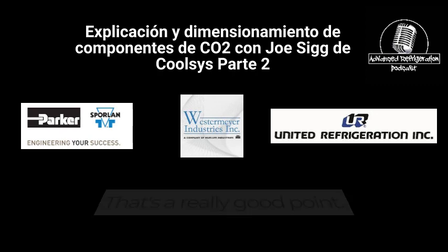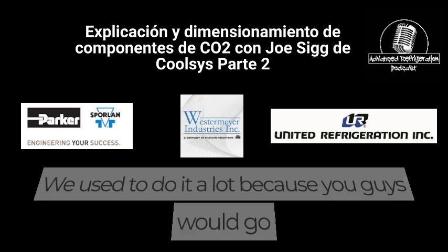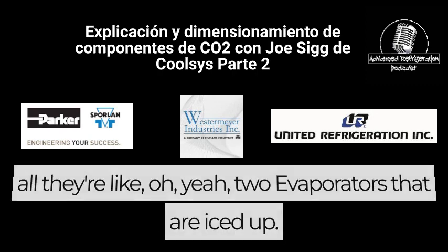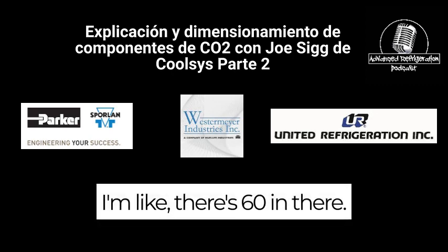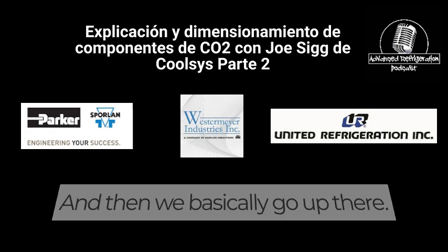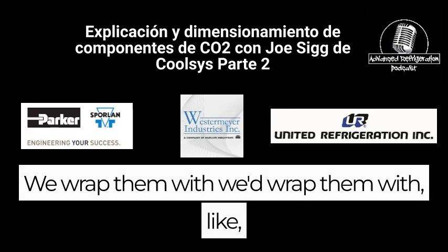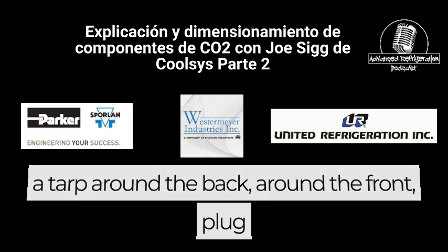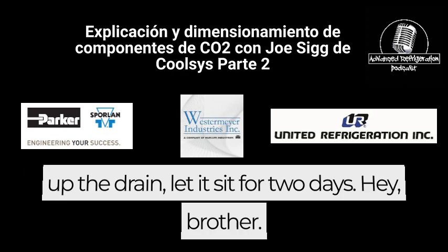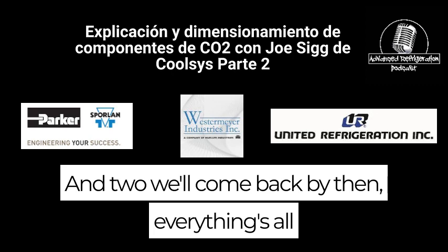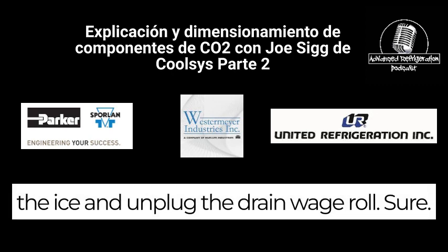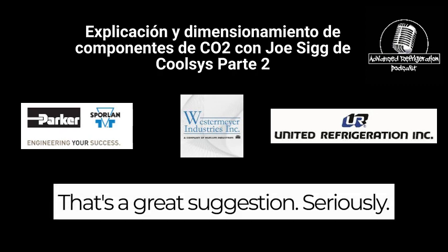That's a good point. That's a really good point. We used to do it a lot because you guys would say, "Oh, we got two evaporators that are iced up." I'm like, "There's 60 in there, I'll see you Monday." We'd go up there and wrap them with a tarp around the back and around the front, plug up the drain, and let it sit for two days. Hey, brother, I'll see you in two. We'll come back, and by then everything's all de-iced, and we unplug the drain. Away you roll. Wow, that's a great suggestion. Seriously.